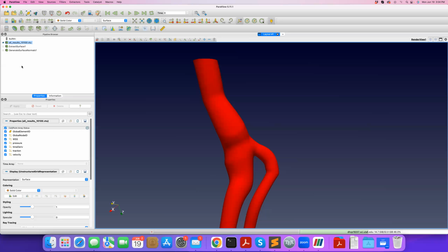But in the newer versions of ParaView, it provides an option where you can select a different file or a different directory, and then apply the state file to that. Everything you've done, even the view and the coloring, will be applied to that other file. Okay, so now let's go over a series of these filters and talk about some of them.